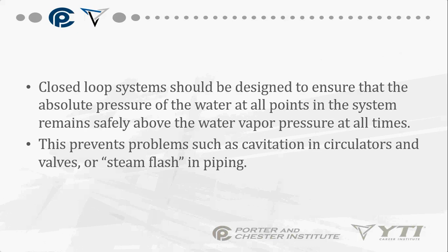Some relief valves will rupture and open at around 35 psi. Which means if the boiler gets up above 35 psi, it will open and it will dump the pressure onto the boiler floor. And usually people have a heart attack and a massive coronary because now they see water all over their boiler. But if a boiler is operating correctly, that relief valve should not open. If it does, we have a pressure problem in the boiler.